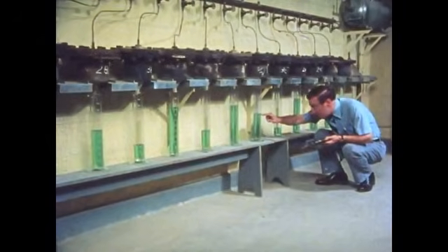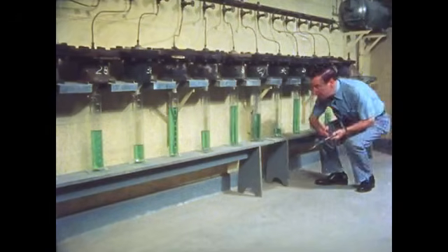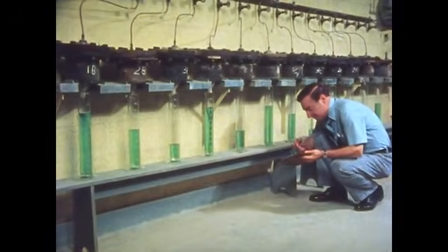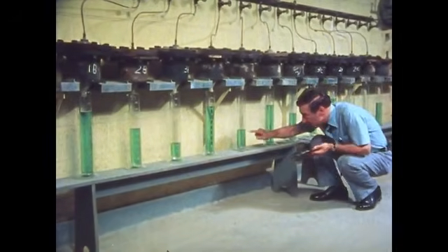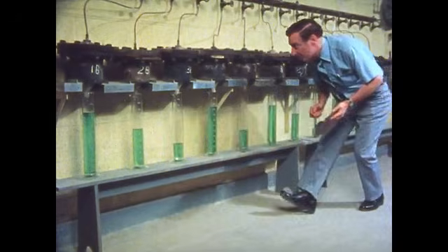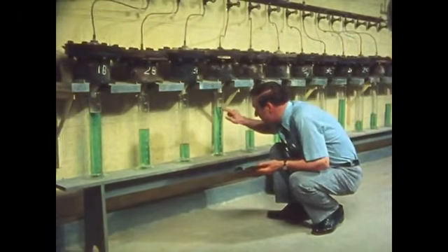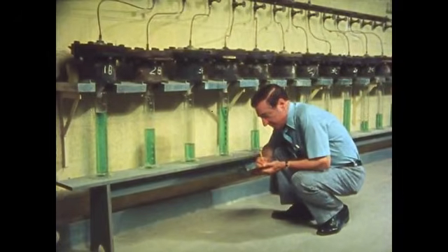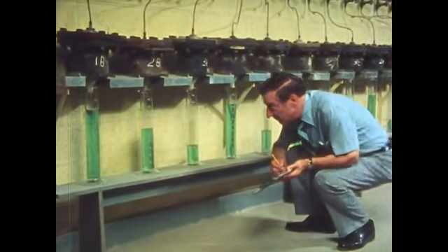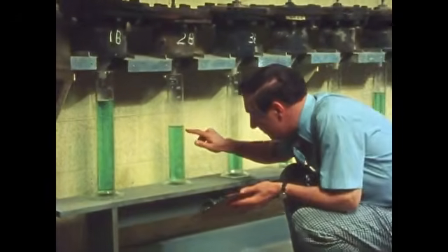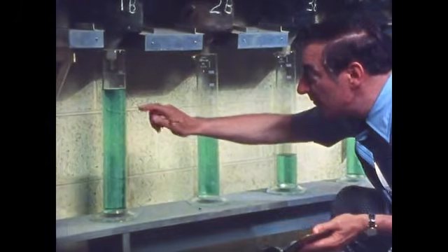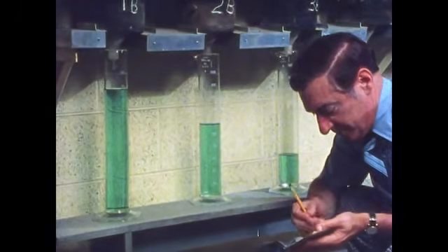Water tightness depends upon the quality of the cement paste. The water tightness of concrete can be measured in this apparatus. Hardened concrete discs of different water-cement ratios are inserted in chambers and subjected to water under pressure for a specified time. Leakage through the discs is collected and measured. Discs with a low water-cement ratio were watertight in 7 days. Discs made from a mix with a high water-cement ratio still showed leakage after 14 days of curing.